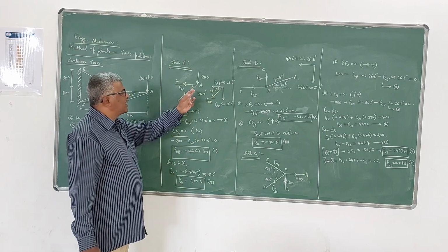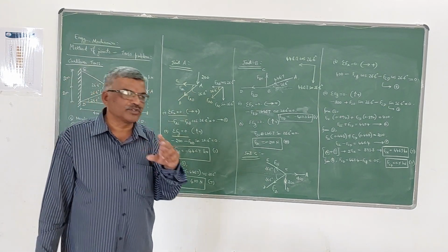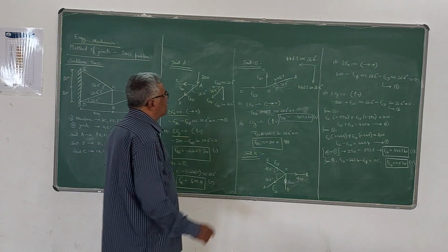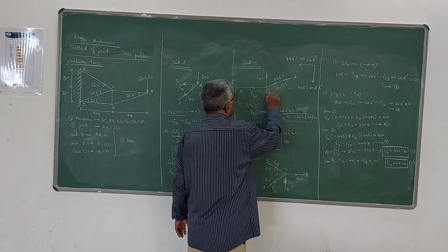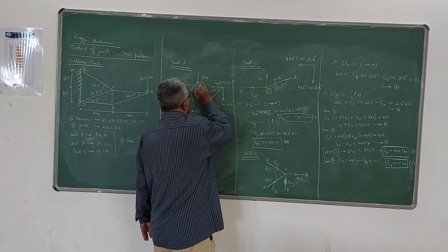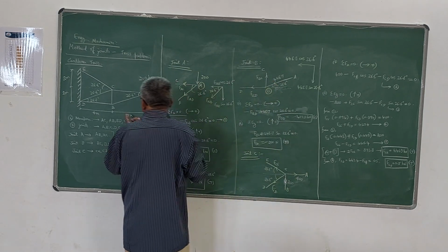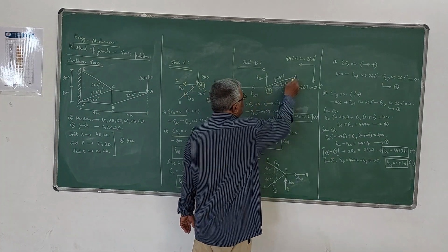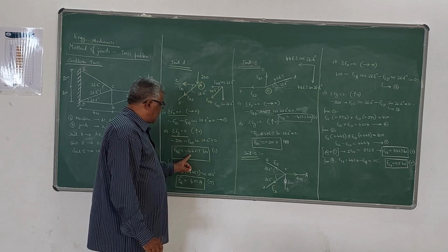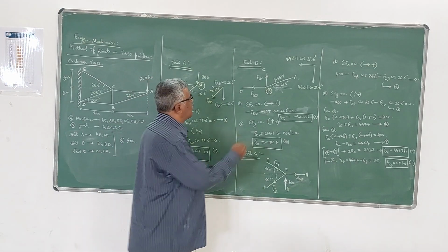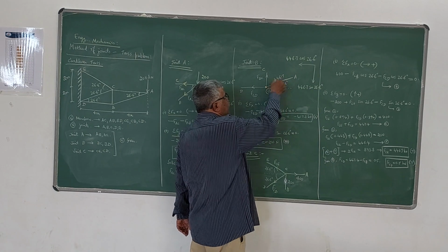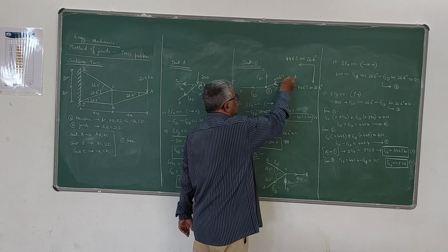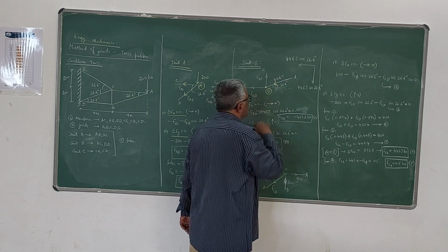Now that means by taking joint A, we have found out two unknown forces in the members AB and AC. Next, come to joint B. So we write down the free body diagram of joint B here. There are three members meeting at joint B: BA, BC and BD. We know the force in the member AB, a compressive force of 446.7. Compressive force means towards the joint, so this arrow will be like this towards the joint, and this angle will be 26.6 degree.